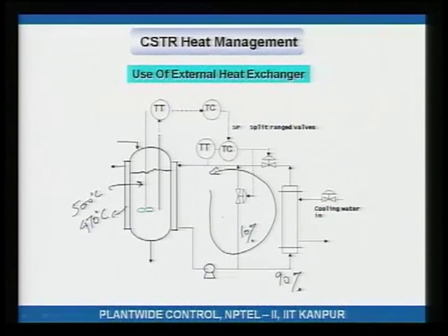Okay. What that means is the master temperature controller, or the reactor temperature controller, is adjusting the set point for the temperature of the hot oil in the jacket. And this slave loop, which is the jacket temperature controller, which is this guy, adjusts the amount of bypassing.